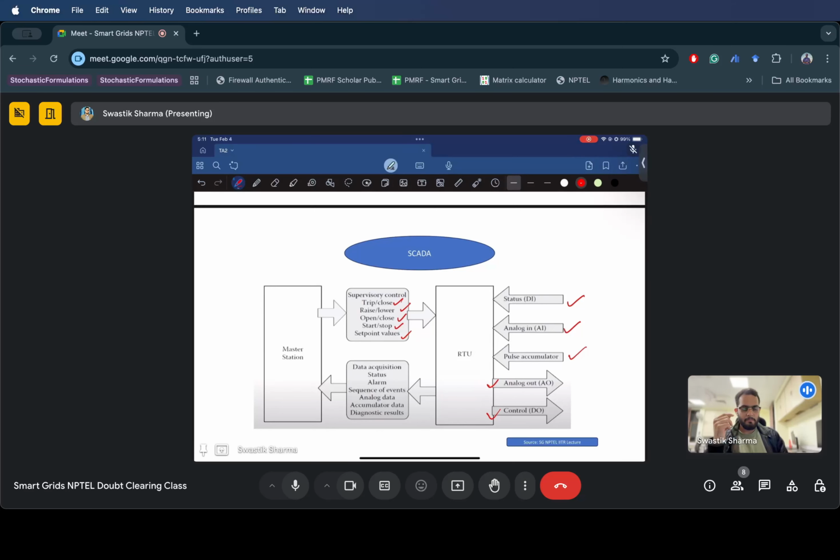It's called a micro PMU, and this PMU can sample data 100 times in 1 second. So what that means is it can sample one data in 10 milliseconds. So that's quite high, right? So you can get a clear picture of what is happening dynamically in the system.